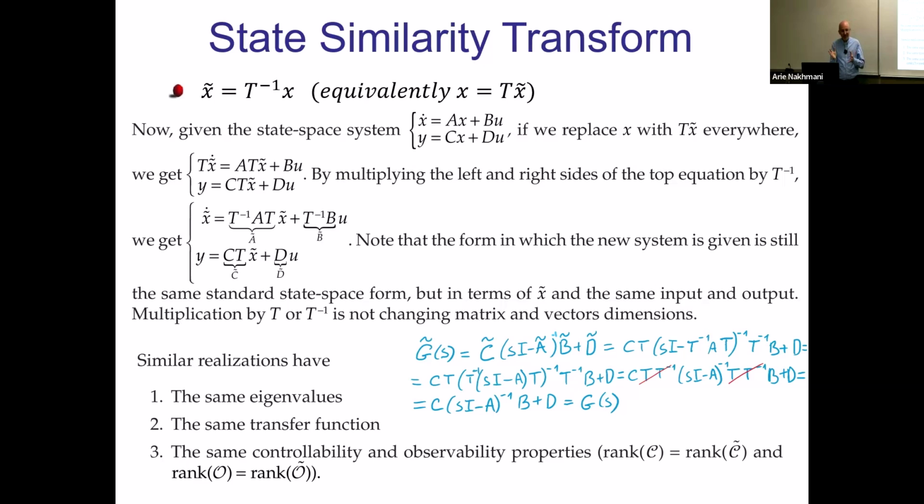So all of the systems will move on the same trajectory. It doesn't matter if you reach a particular state, you cannot redefine the system from the middle of the way into a different system, because for that system, the state will be completely different. You can translate it into a different state. So your x0 for that system will not be the same x0 for the other similar system. So you need to translate it by multiplying by T inverse, right? And then if you start with that new initial condition, you continue on the same trajectory.